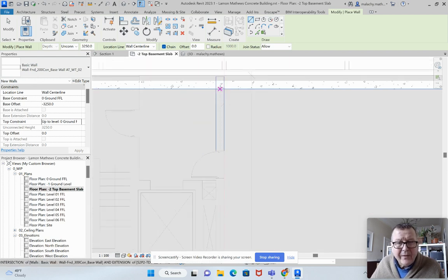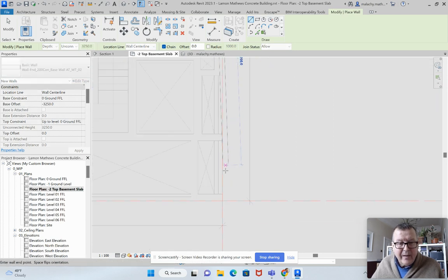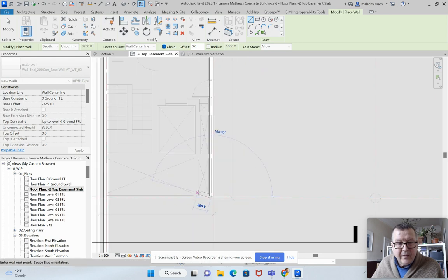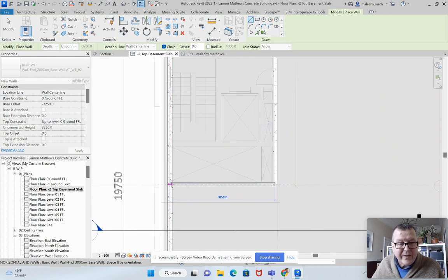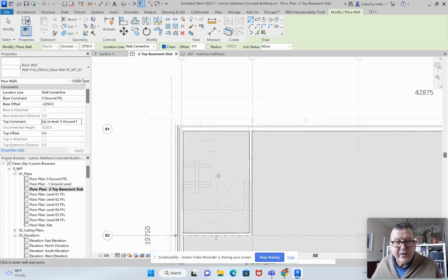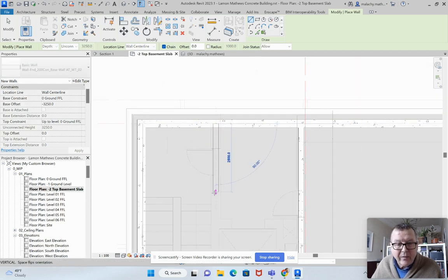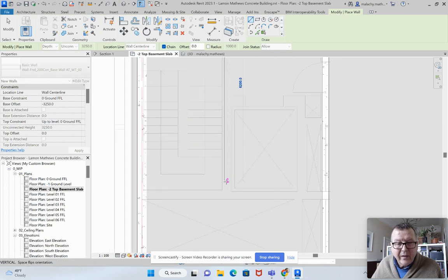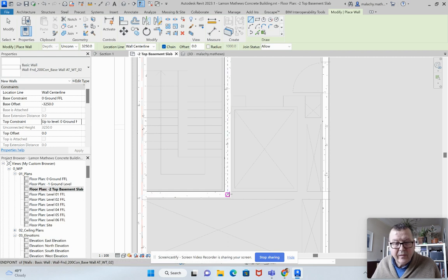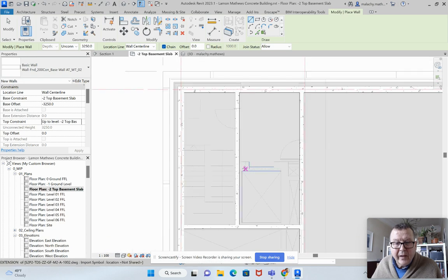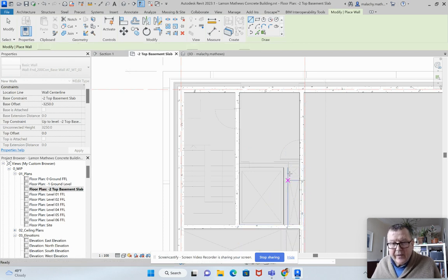So now this is where the AutoCAD plan comes in handy here. Revit will recognize that there's some vector information here that it can use. So again, I'm going into center line here, and I'm just following that path of walls that way. Okay, and we'll come across here, I think as far as there. So there's a little bit of a service cavity by the look there.